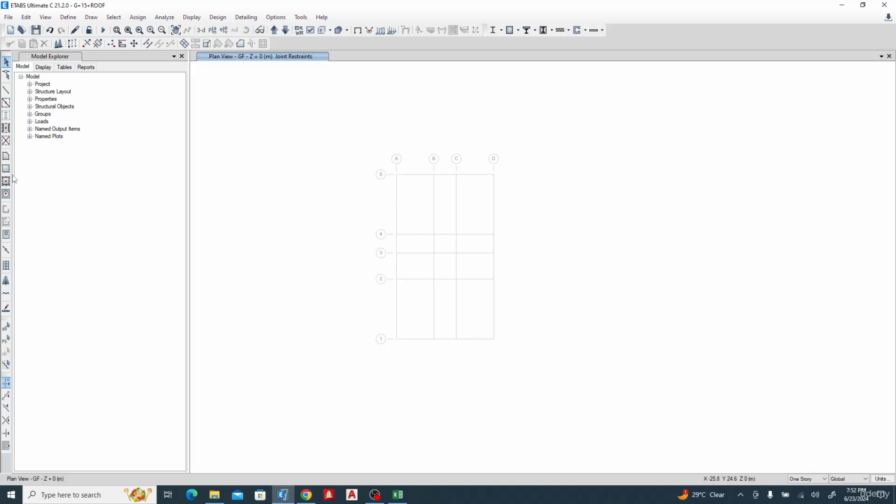So what I'll do is I'll come here for my slab. Okay, sorry, select this, choose the property for my footing, pad base 750. What is my x dimension? We said 3 meters, so that's 3000, and this is also 3000. Okay, so I'm going to place one here, place another pad base, place another pad base.